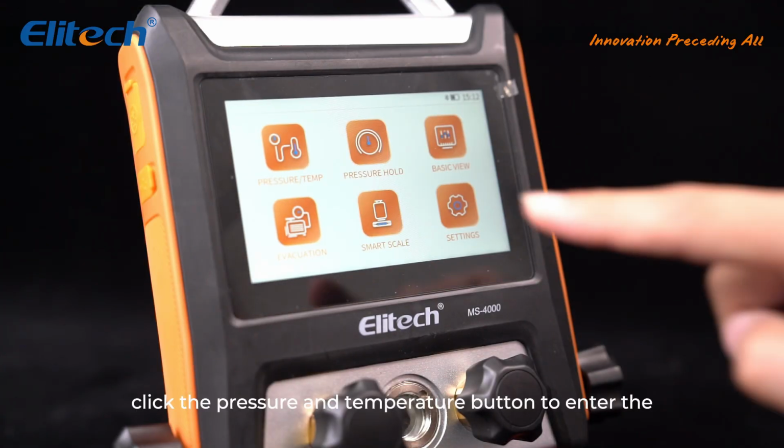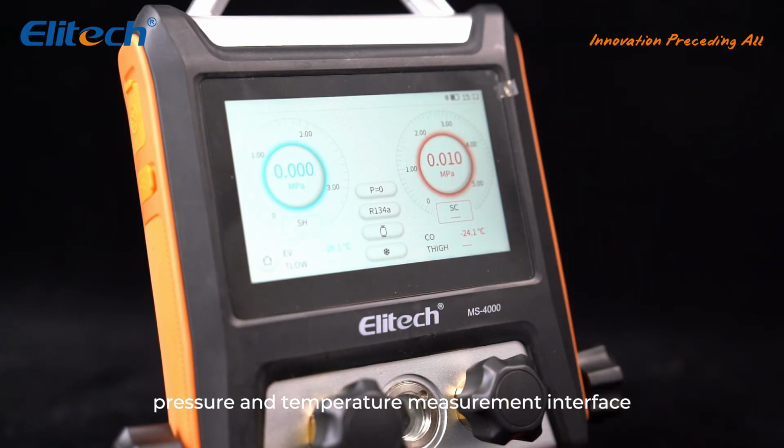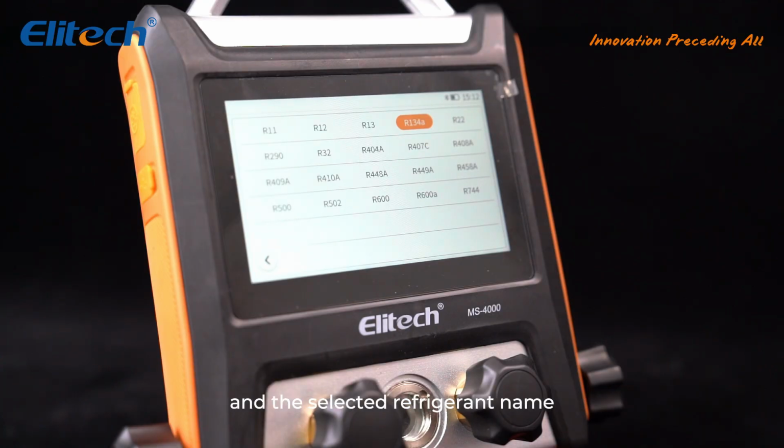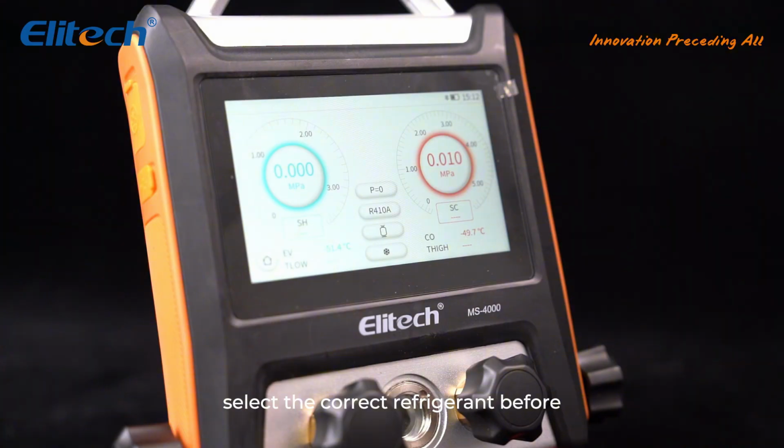Pressure measurement. Click the pressure and temperature button to enter the pressure and temperature measurement interface. Click the refrigerant button to select the refrigerant, and the selected refrigerant name will be displayed on the button icon. Select the correct refrigerant before use to avoid affecting the temperature calculation.